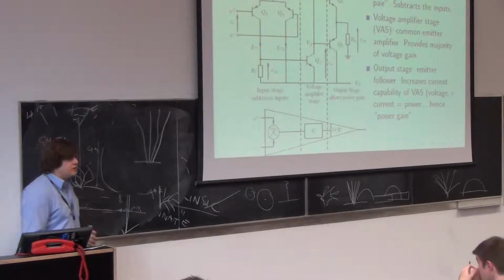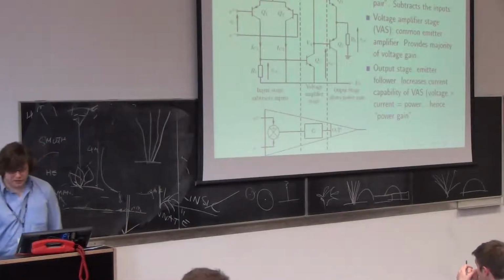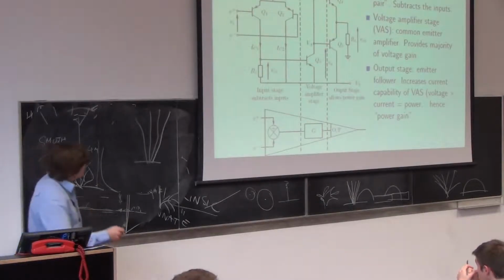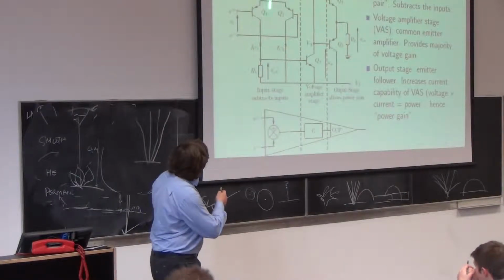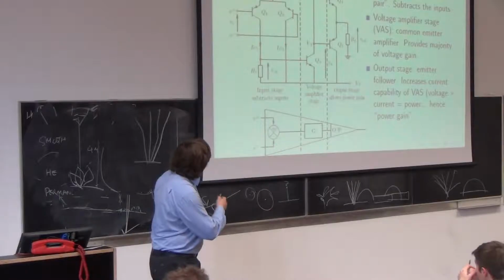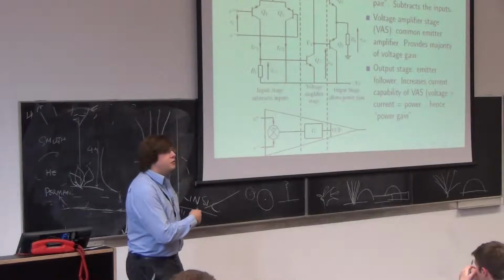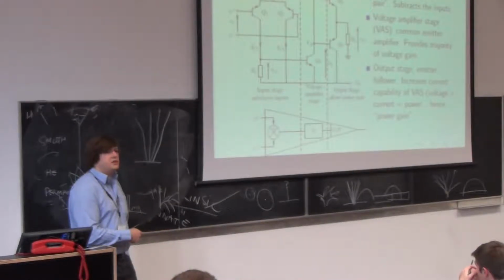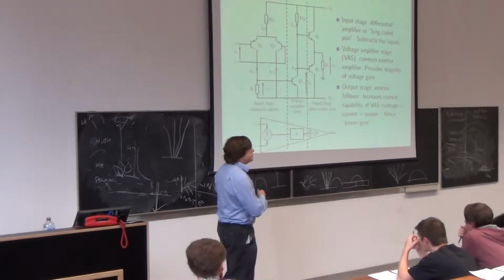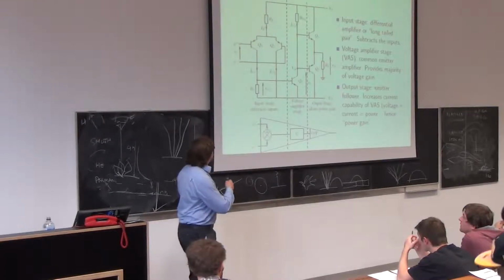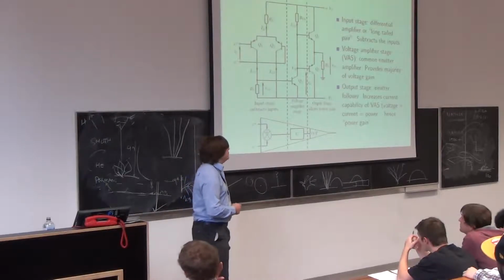So we've seen this diagram before. It was in the end of the last set of slides as well. We have 3 stages. Got my lightsaber. So input stage, which is a differential amplifier. These 2 transistors share a tail current, which gets split up evenly between IC1 and IC2. Ideally evenly. It's your business as the designer to make sure it is even. And if you don't, then the operation of the stage will not be optimised. You'll have different base currents, lots of weird stuff which you can read about if you want to.